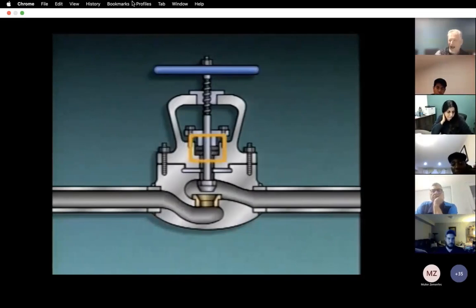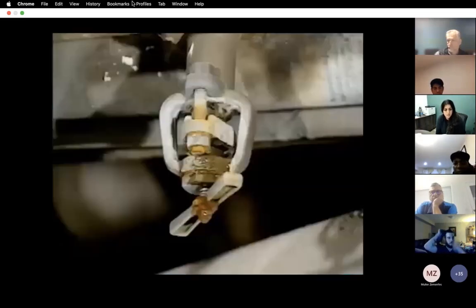The stuffing box holds the packing, which is installed around the stem. The packing is flexible and leak resistant. It prevents leakage from the valve along the stem. The pressure applied to the packing by the packing gland is adjusted using gland nuts. The pressure is adjusted so that the valve stem can be moved as the valve is repositioned, but leakage does not occur around the stem.